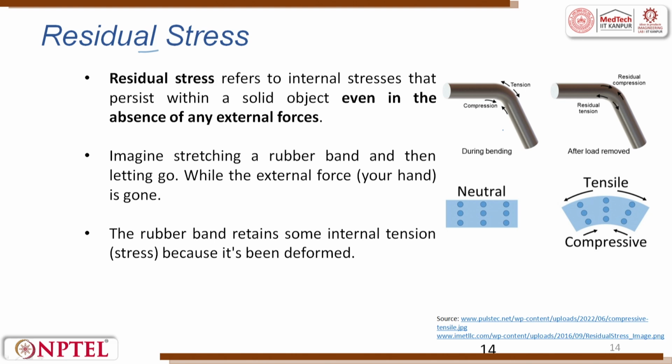Residual stress. Residual stress refers to the internal stress that persists within a solid object even in the absence of any external force. So, you bend and keep, slowly what will happen? It will try to relax. When you try to bend a pipe, you will see here at the top end skin, there is a tension or a tensile stress coming.